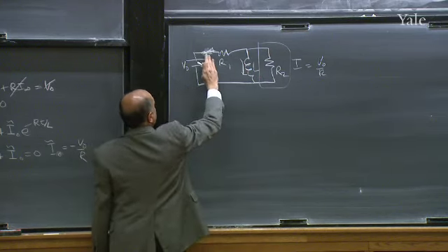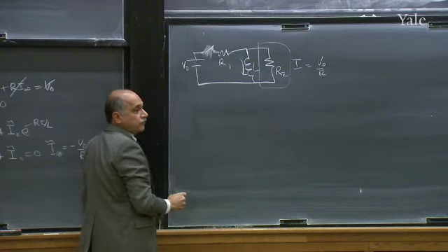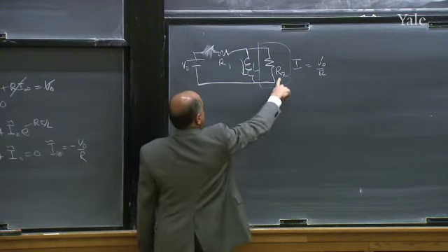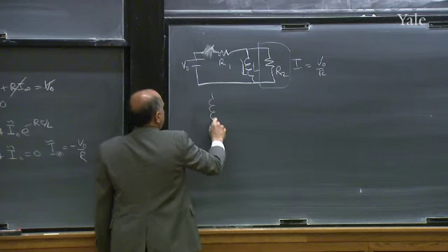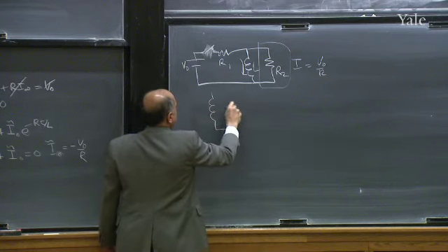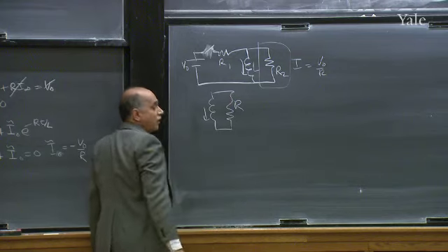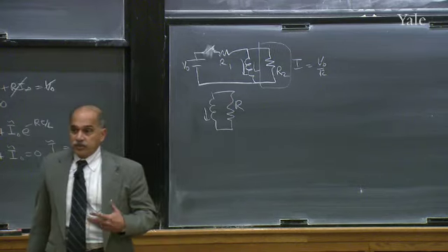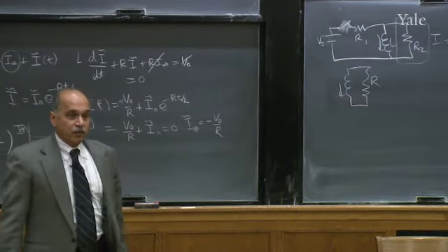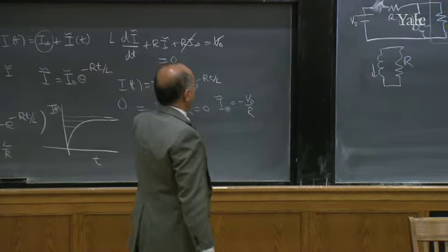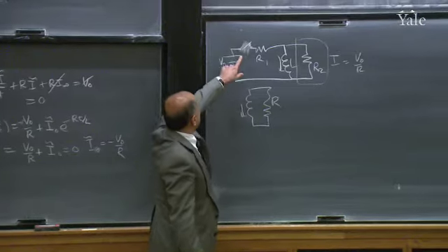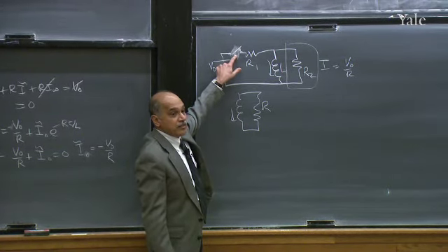But now if you throw this switch open, you have given it a path to discharge. So the inductor will discharge through the resistor. The current will continue to flow in this direction. Of course, it cannot flow forever because the resistor will burn up the energy. But you're giving it a path. You're avoiding, in a way, the air, which is also a path with very, very high resistance.